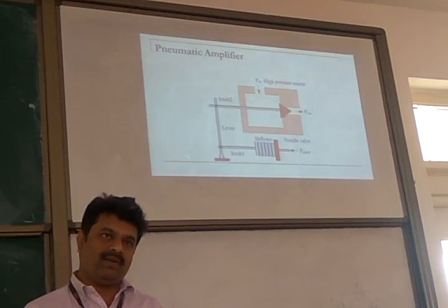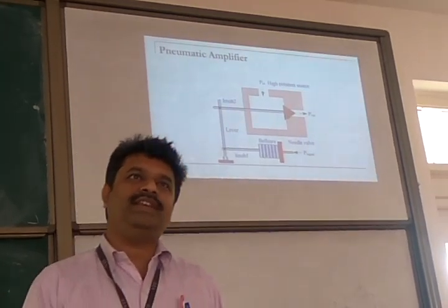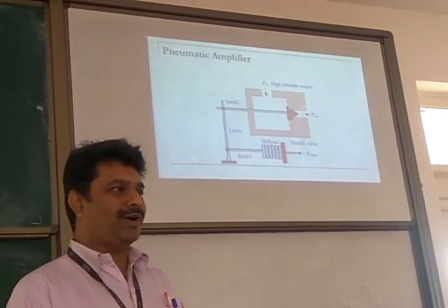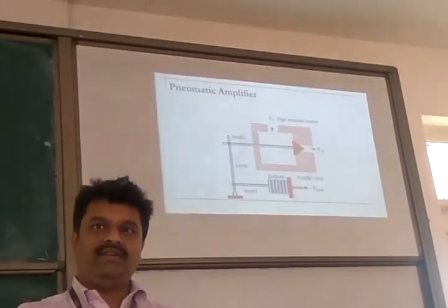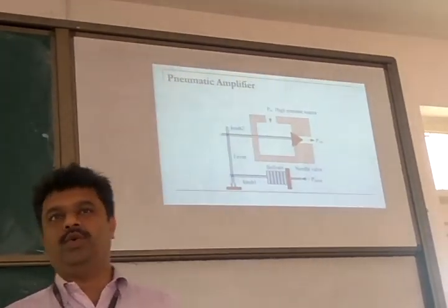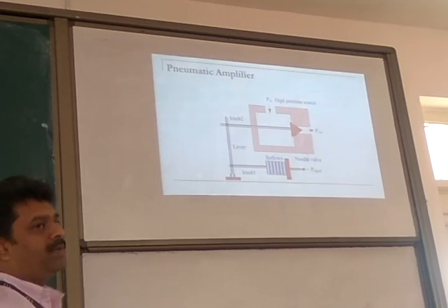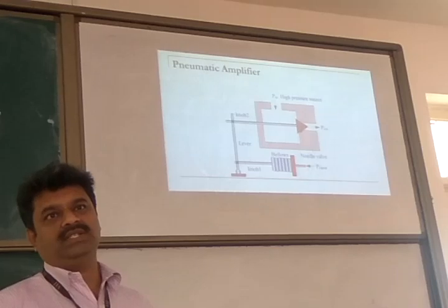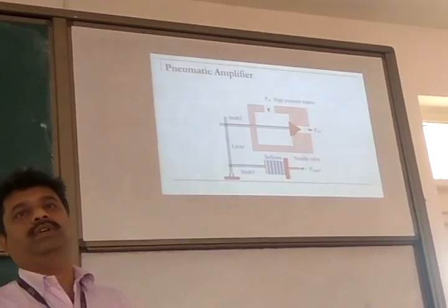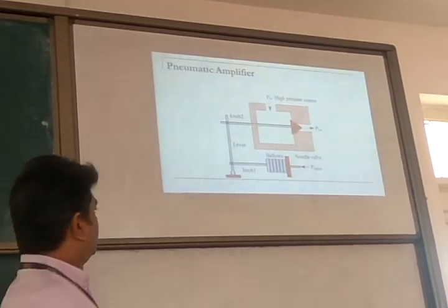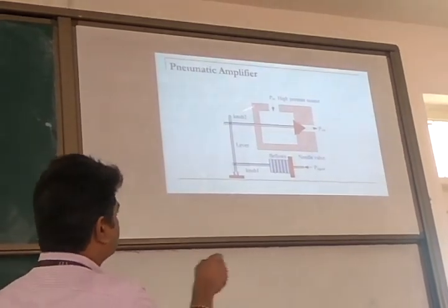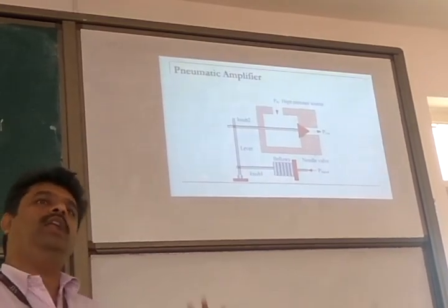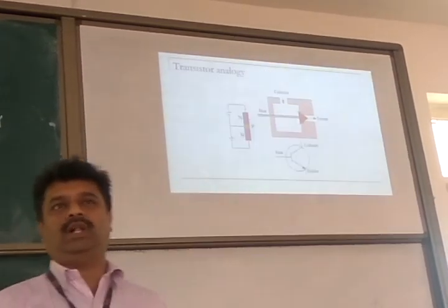So the power level is amplified, amplitude is increasing, external power supply is used, and faithful reproduction, I forgot to say: whatever is the variation in the input, the same variation you witness in the output. So that's a faithful reproduction in the output. So this device can be called an amplifier. You simply put everything inside the box, and you have this as input, this as output. All your conditions are satisfied for an amplifier, so we will call this an amplifier.